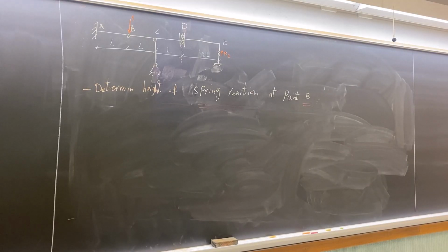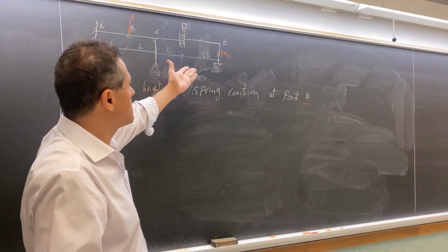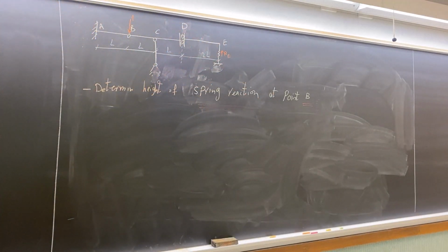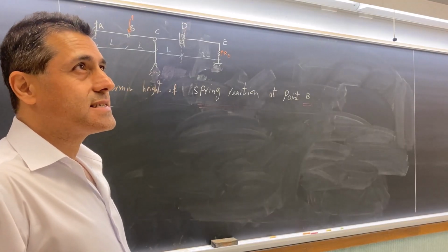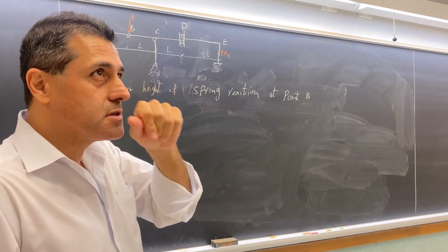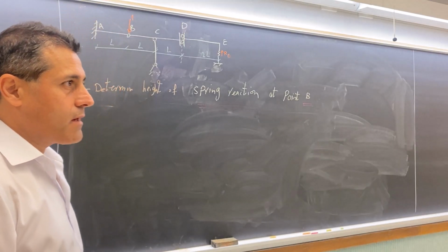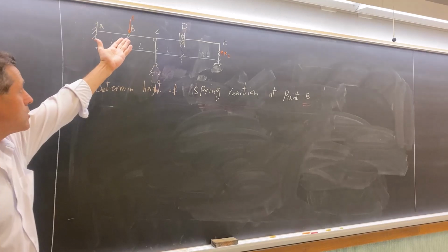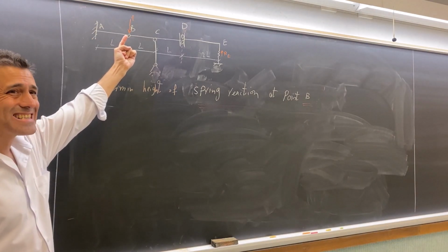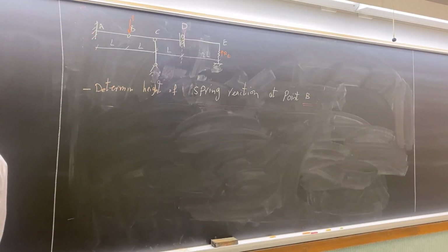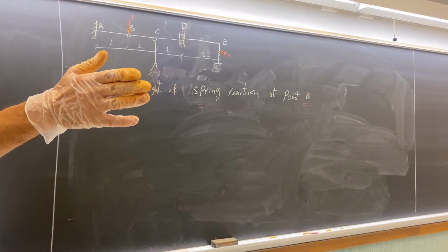So from here, this is not structure analysis, this is statics, because you place a unit load here and then you find RE, so it is just statics. But now, you never faced this issue when you passed statics. If I was the instructor, I told you, and I think I was the instructor in statics, the unit load is exactly at the axis of pin B. Where should I place it? Right side of B or left side of B? Because this is a question.